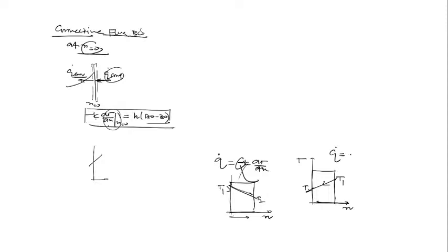Yes, it's a plus. Why is it correct mathematically and physically as well? Because the minus sign in Fourier's law only indicates that in the direction of increasing x temperature decreases. Here, in the direction of decreasing x, temperature also decreases. That's why there is a plus sign.